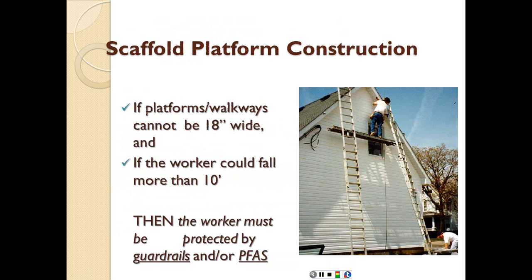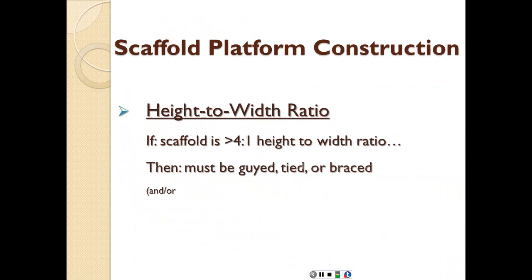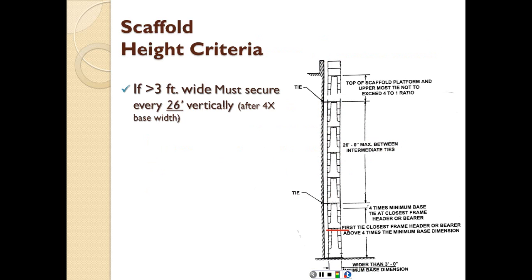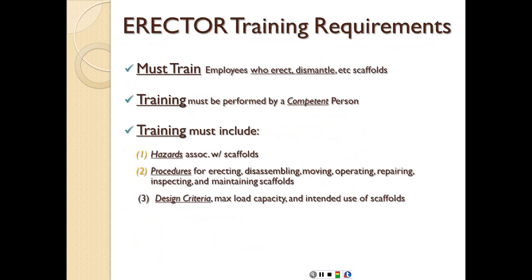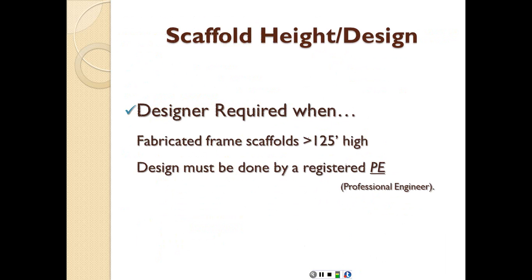And that also applies to things like heavy construction. If you're going to have a bridge, for example, or something like that, then definitely that's going to be done by a designer. It's not going to be something for anyone to do. The design must be done by a registered professional engineer. If you remember, we have seen that when we were talking about excavation. If the excavation is going to exceed 20 feet, then the support is going to be designed by a professional engineer. Here's another area where a professional engineer is going to design some part of our work that we need to perform.